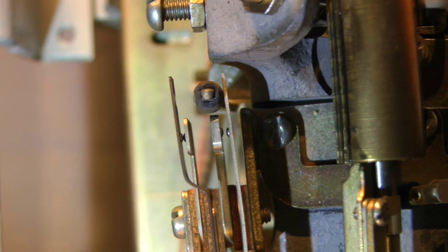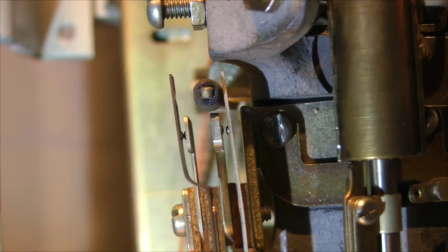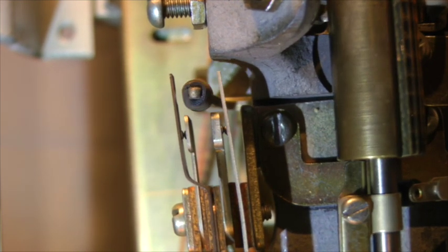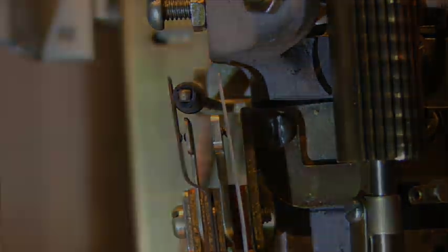Each time the armature returns to its released position upon de-energizing of the rotary magnet, the lever pivots back to its normal position, releasing the rotary interrupter springs. So the rotary interrupter contact springs operate and release for each rotary step of the shaft. They form part of the control path for the automatic rotary stepping process.